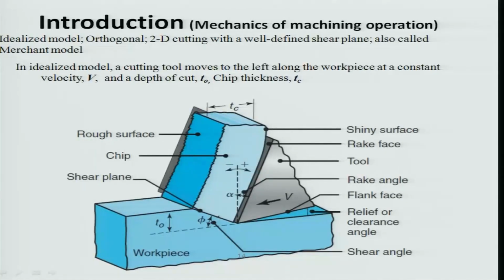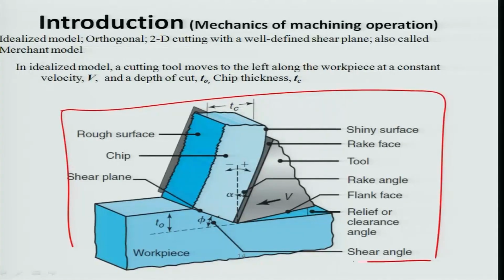This is the peeling action which is going on here, expressed in this particular figure. So, this is the uncut surface, and you have a tool point or a tool tip, which is actually a single point tip, but there is a cutting edge associated with it, and it moves with respect to the workpiece in a direction parallel to the direction of movement of the workpiece.